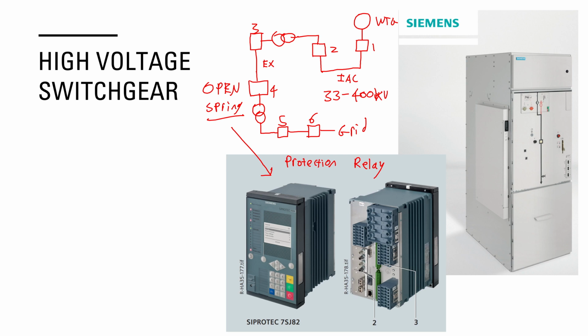And the way it opens the switchgear is usually there's one solenoid in the switchgear that when it opens, it moves a physical mechanical latch which allows the opening switchgear to spring in, and there'll be a bang and the switchgear will open.